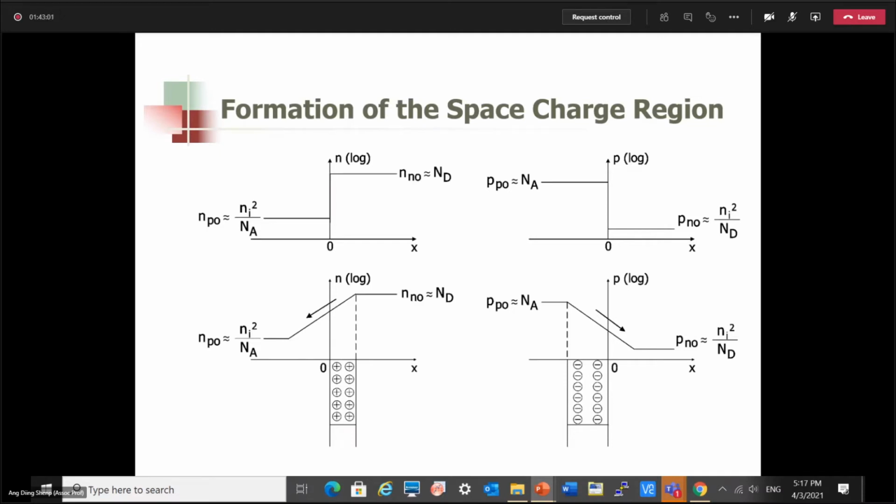Remember? And the second correction is that a P-type semiconductor, you cannot think of it as a positively doped semiconductor. That can lead to confusion. Although holes are the majority carriers in the P-type semiconductor, and holes are positive charges, that doesn't mean a P-type semiconductor is a positively doped semiconductor.